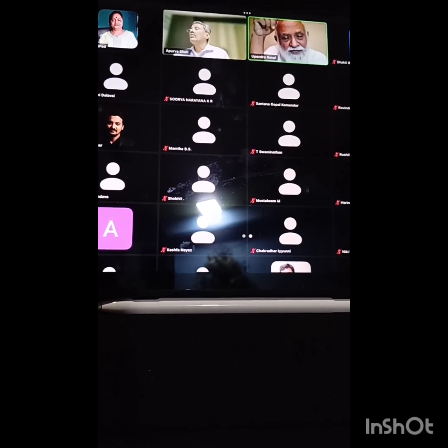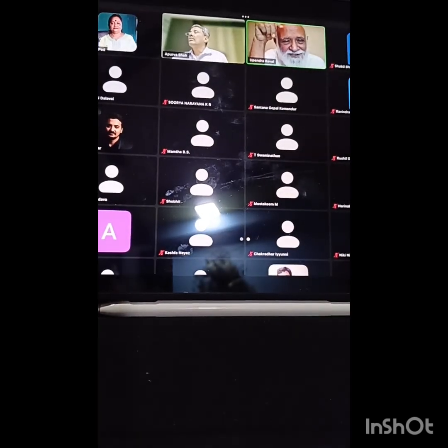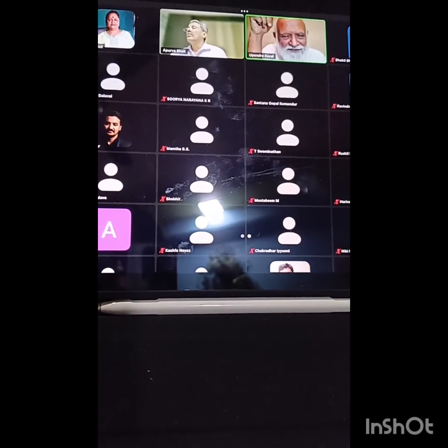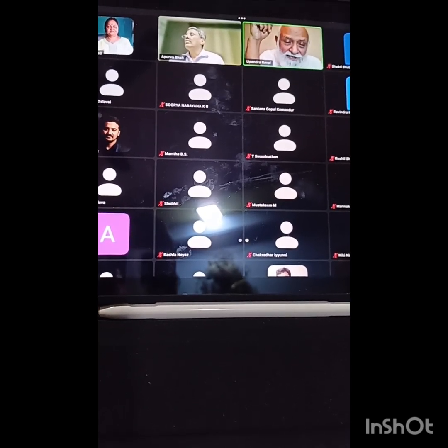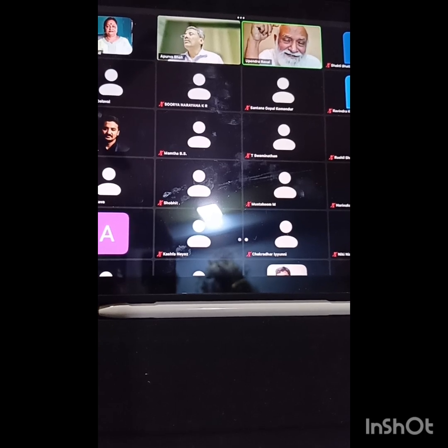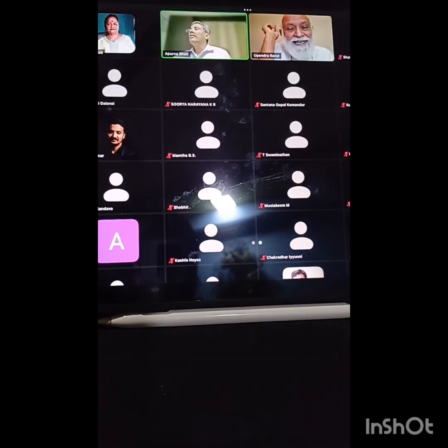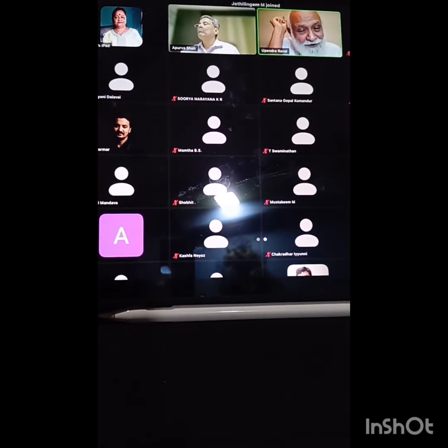Apurva, sorry for my interjection. The point is, the acid-cement neutralization reaction has a maximum of 18 to 20 years of life. So the pipeline you are talking about is 30 to 60 years: 30 years up to 2 feet diameter, and above 2 feet diameter it is 50, 60 years. But the joint cement strength holds true only for 20 years. Yeah, the leakage starts from there onward.